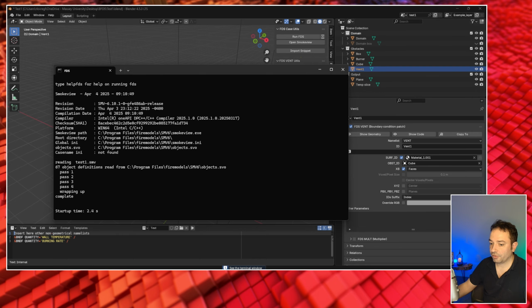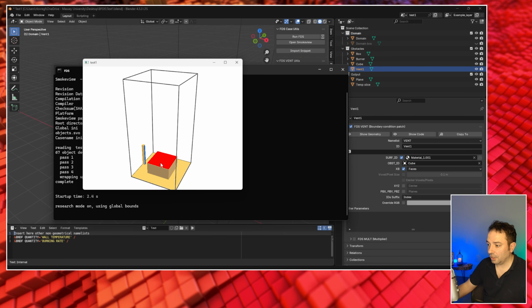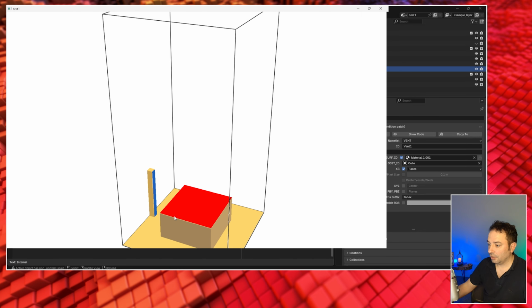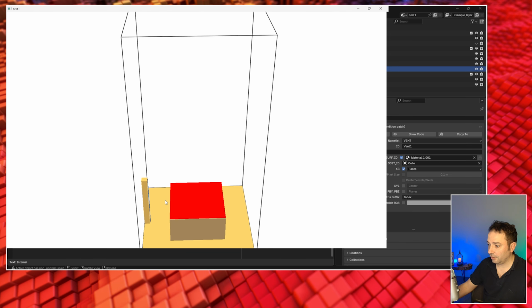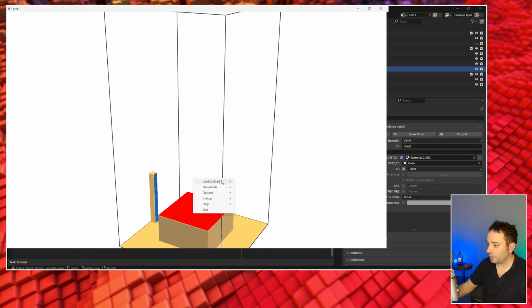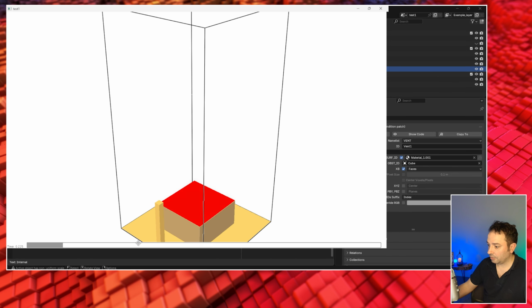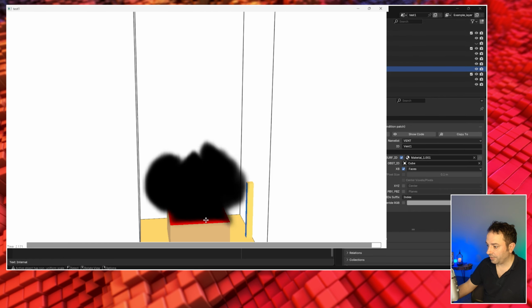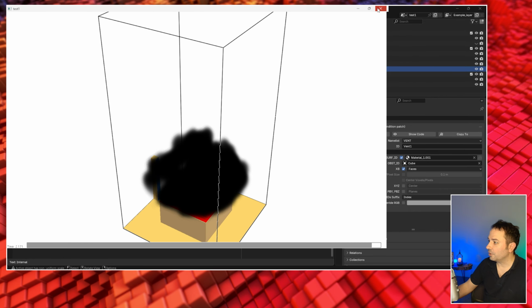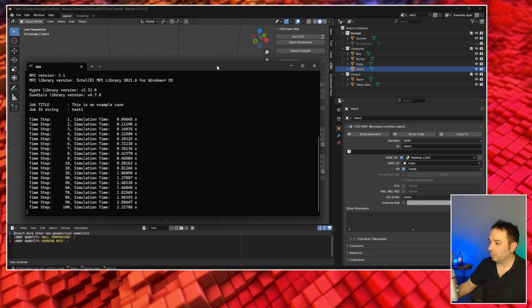So Smokeview is opening as well, and you can see that the new element has been included, and we have also a nice vent here. Let's see if it's working within the simulation. So let's see the impact on the smoke. So you can see here that probably we don't have enough simulation time. So let's wait a bit for FDS to run more seconds.